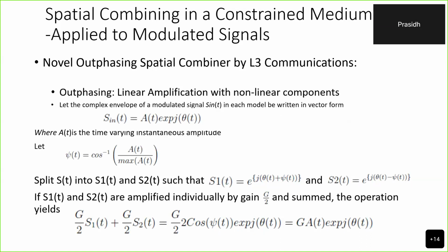Now the thing is, in none of these did we see any mention of parameters related to wireless communications, like peak to average power ratio. Because when it comes to wireless communications, particularly terrestrial ones, we are not going to operate with constant envelope modulated signals. Most of our signals here are essentially OFDM, which exhibit a high peak to average power ratio. That being the case, can amplifiers like these, or can spatial combining, be applicable to amplify modulated signals faithfully and efficiently? This is a question.